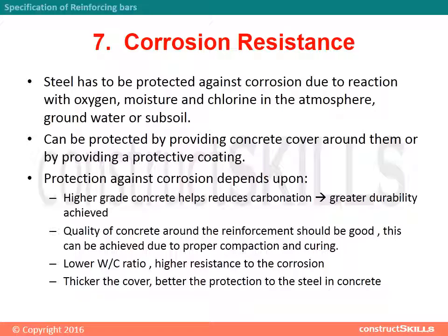Corrosion resistance. Mild steel or high-yield steel has to be protected against corrosion due to reaction with oxygen, moisture and chlorine in the atmosphere, groundwater or subsoil. The bars are generally protected by providing concrete cover around them or by providing a protective coating.